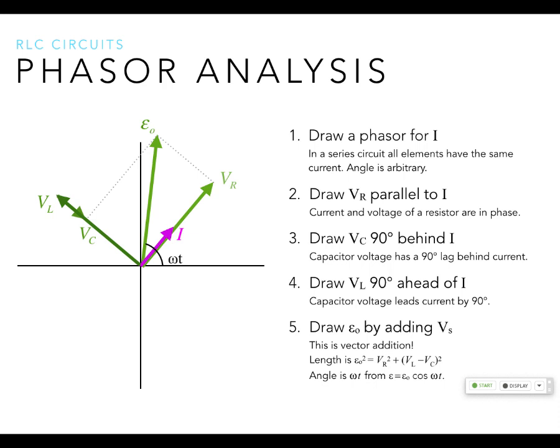Now that's what's tricky in the RLC circuit, because this is what you put in, even though we found it last, okay? So that means if this is relative to this, the angle between here and here, that's not omega t, that's not pi over 2, it's not 0. There's an angle here, okay? And the relationship between the current through the circuit and the voltage source has an angle, has a phase difference. And that's what we're really worried about, because that's how you know how your circuit's operating. And we'll talk about what that means in a second. But this is called the phase angle.